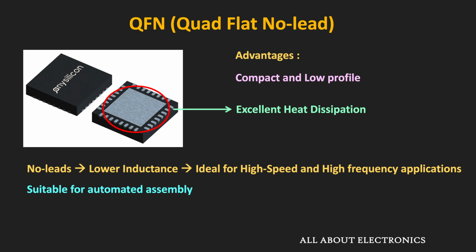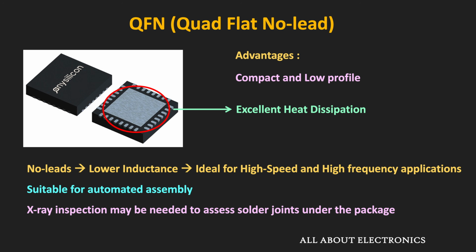Now the only difficulty with this package is that as the solder joints are under the package, through visual inspection, we cannot see the soldering. And therefore, to check whether the soldering happened correctly or not, we need X-ray inspection.